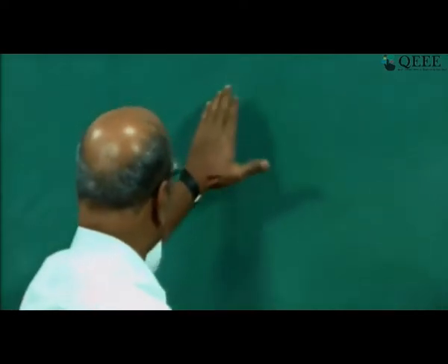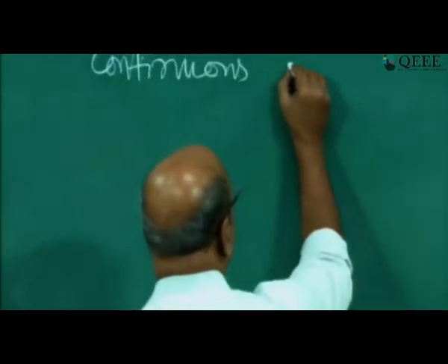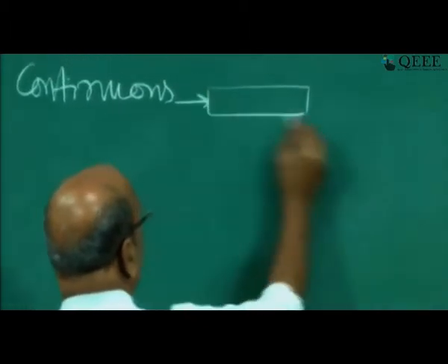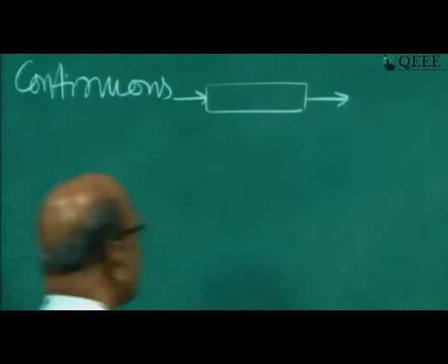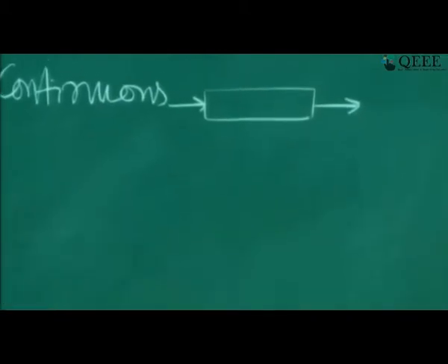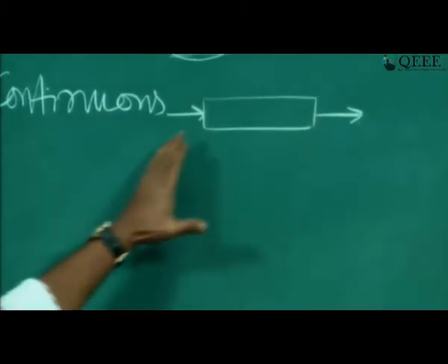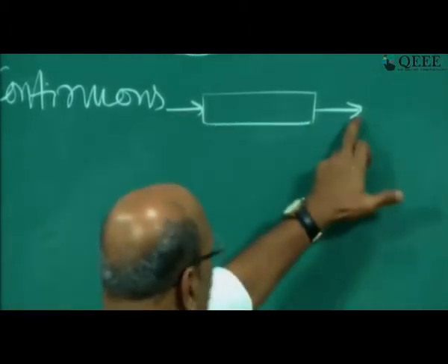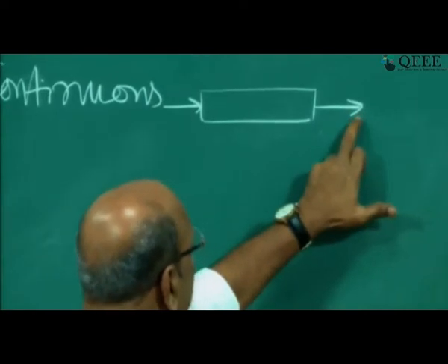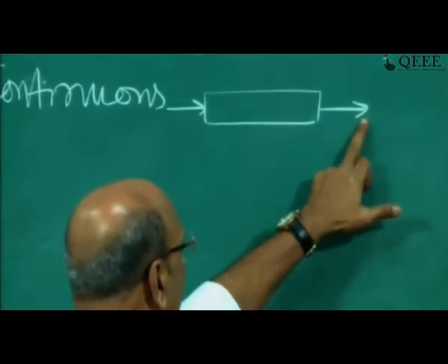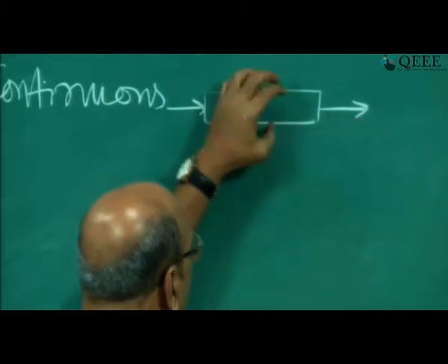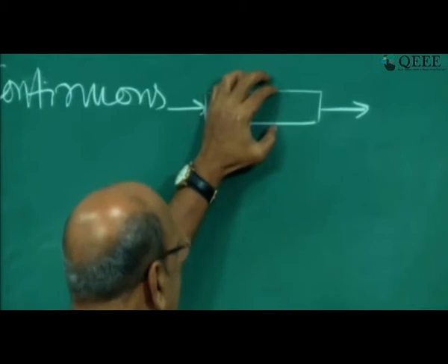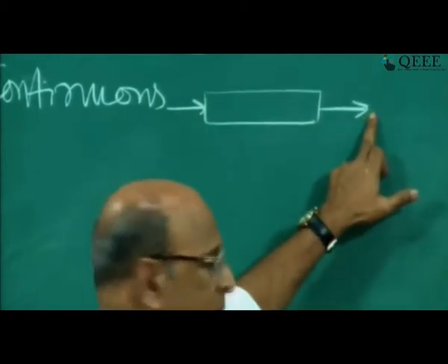equations. In a continuous system, what we do is we take any vessel and then continuously you feed and continuously you can take out the product. So this is a continuous system where you feed all the reactants continuously, and product is coming continuously. At this point what you have is the conversion. Now if you have an old, existing reactor, you don't have to calculate the volume of the reactor, but you have to calculate conversion.